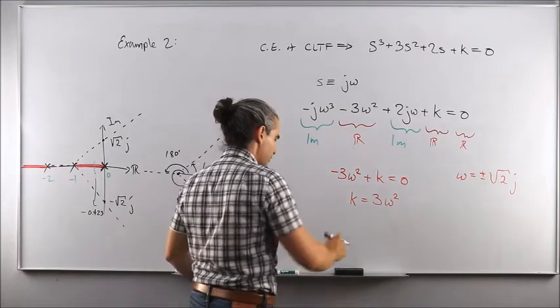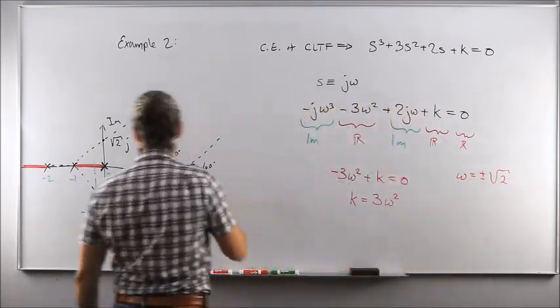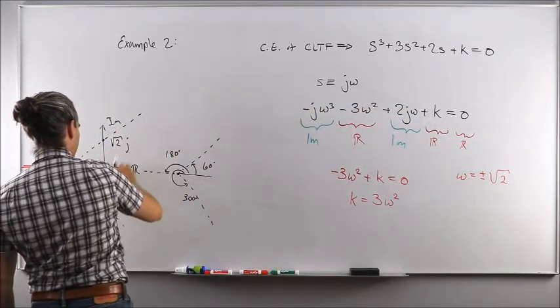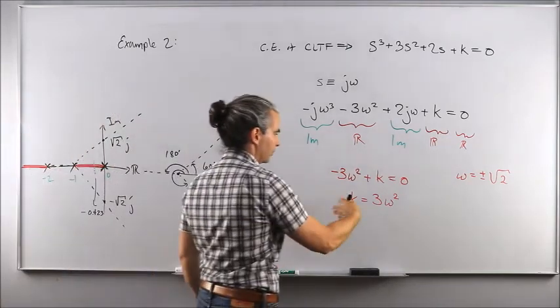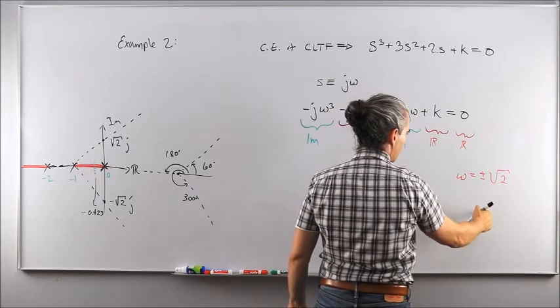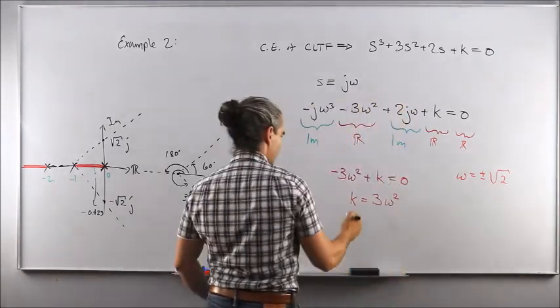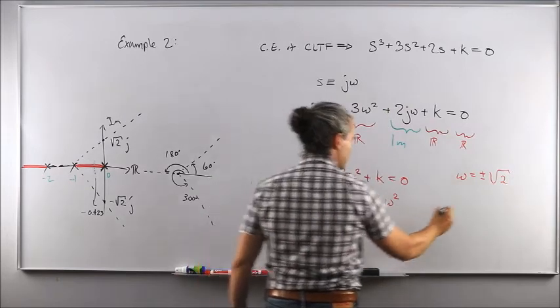Omega is square root of 2, okay? The location is omega j, so that's why you have to report the j here. But for your hand calculation, we had obtained omega equals plus or minus square root of 2 and 0. So you're going to cross the imaginary axis, right?